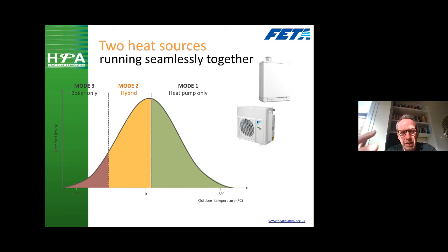that you're using. So in a hybrid or bivalent mode, what we're looking to do is utilize the heat pump when it's more cost effective and more carbon beneficial to do so. In some instances, we can run the two modes together. And then finally, when it's the best time to do so, the fossil fuel system can take over. So that's how hybrid works.